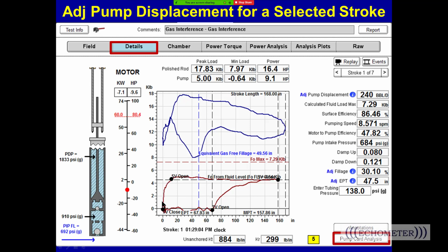Now, this could be gas expansion or it could be slippage. We lose part of the stroke due to slippage, because there's slippage required to keep the plunger from sticking and to lubricate the plunger during the stroke. You have to have some, but if you have a large clearance, it can be a lot of slippage based on the discharge pressure and the clearance.